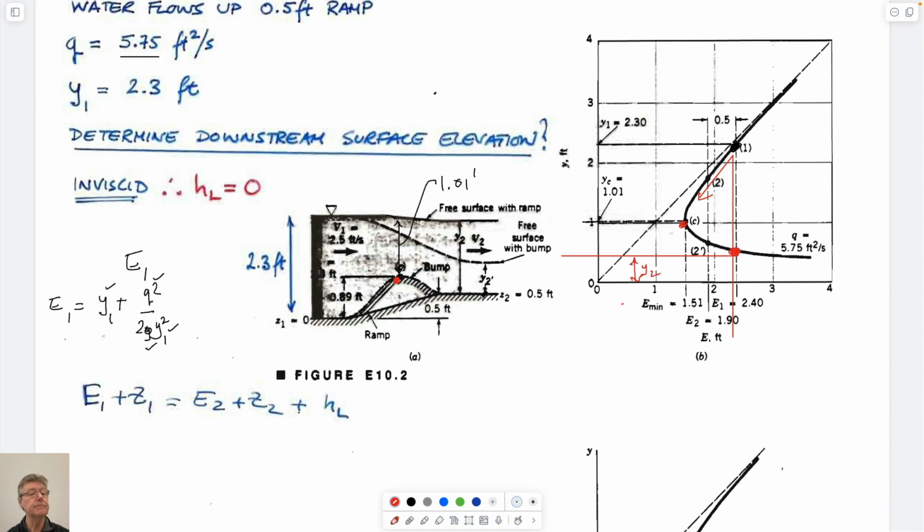This flow here. And so you go from upstream subcritical to downstream supercritical. To get from subcritical to supercritical, you have to have some way to get there by going down this trajectory, because the volumetric flow rate per width isn't changing. This is the curve for all of those different depths. And so you have to get to this nose to be able to get through it. And that's what changes you into a different flow regime.